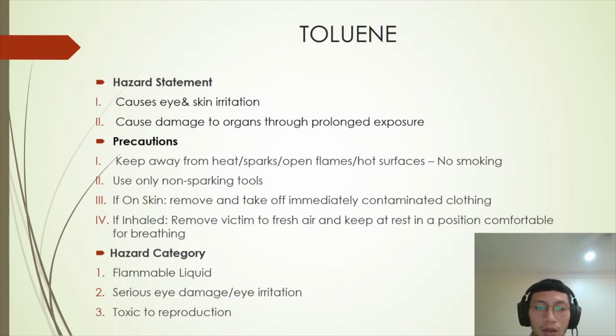After that is about the precautions. Firstly, keep away from heat, sparks, open flames, and hot surfaces, and no smoking near it. Besides that, we can only use non-sparking tools. After that, we have to make sure that we use explosion-proof electrical, ventilating, and lighting equipment. We also have to wash thoroughly after handling it.